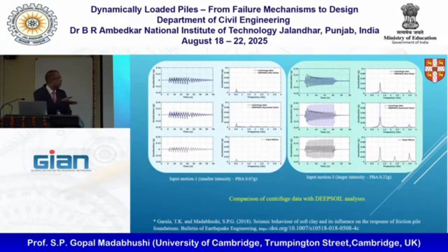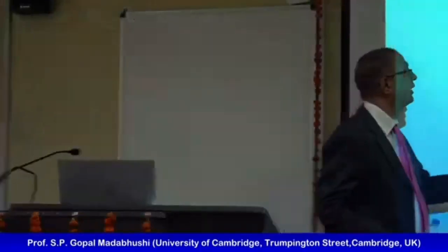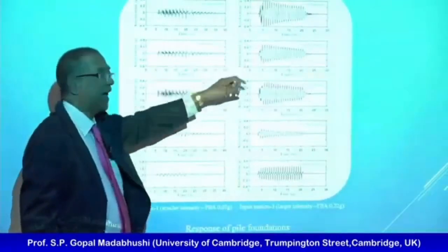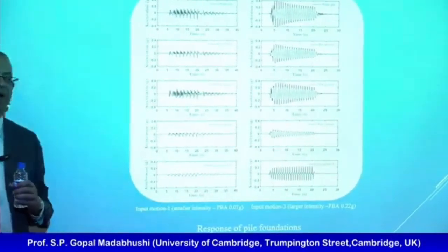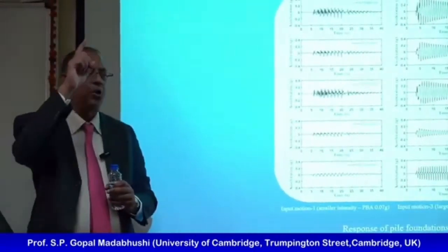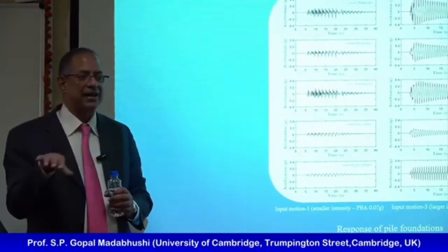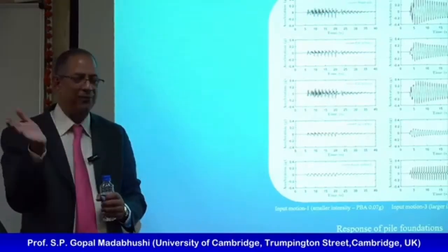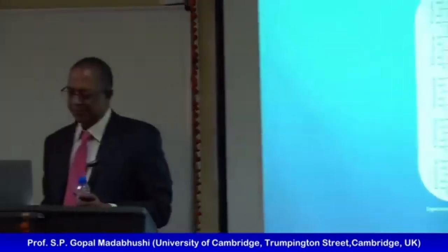And you can also see the pile response. If I apply the big earthquake, although the clay doesn't respond, the top of the piles actually oscillate a lot. That's because I use the pile to connect the stiff part of the clay to the top. So the rest of the clay gets protection because it gets isolated, but the pile itself will carry the load and oscillate quite strongly. Okay, that's all fine.